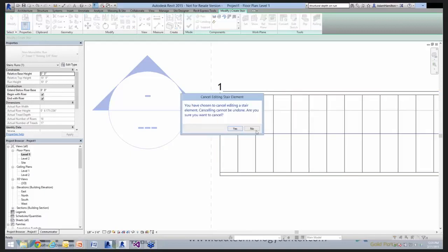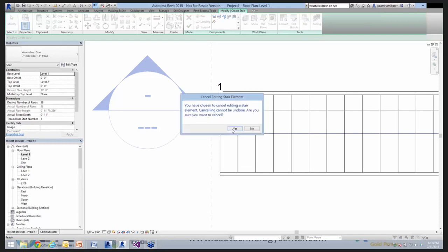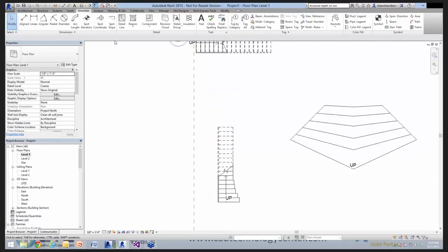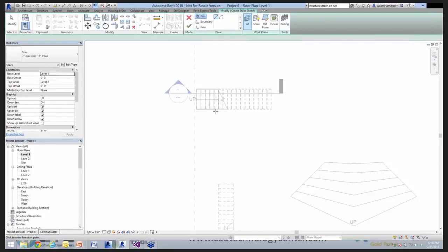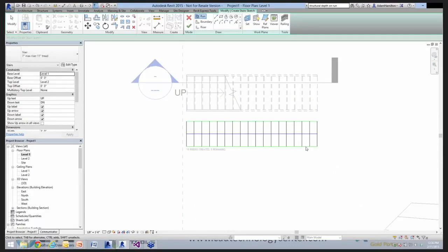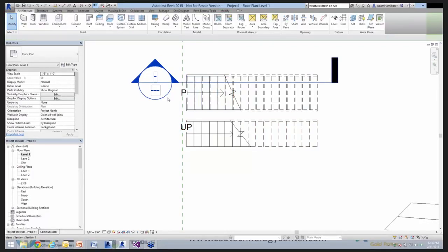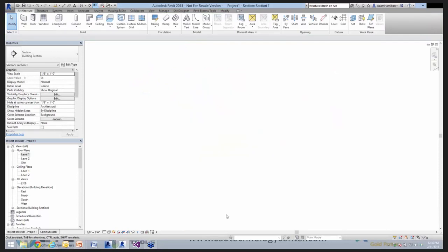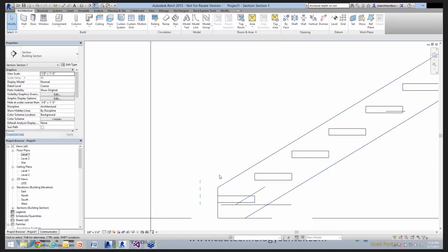So there are times when a stair by sketch is still important. If I was to create using the same idea, I go to Architecture and use the stair by sketch tool, and just a standard run. I hit okay, and pull this guy down here. Again, by default the support stops at the edge of the stair.